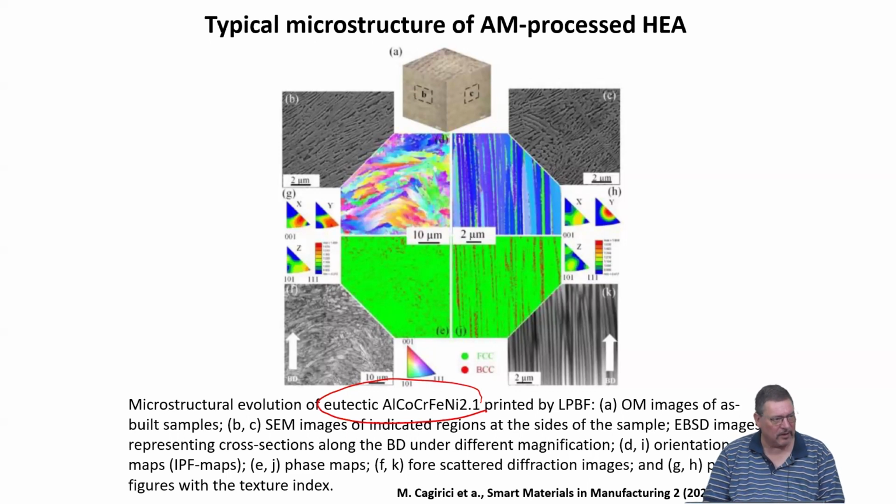And one needs to really always analyze also the microstructure in all three different directions in order to get a full image and full picture of what really is the microstructure of the material. Just doing a planar cut through the microstructure like you normally do, polishing and looking at the cross-section, is not enough. You have to look at three cross-sections which are perpendicular.